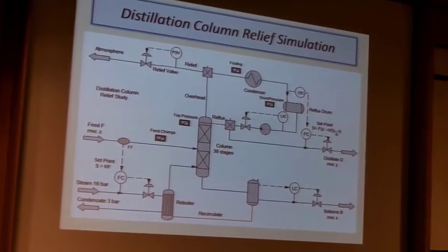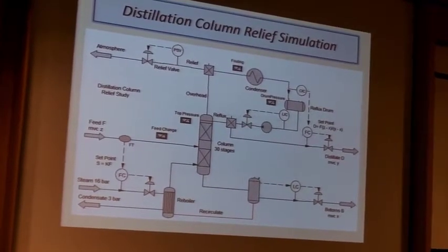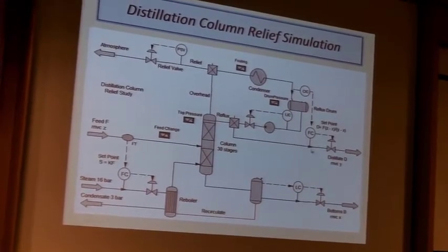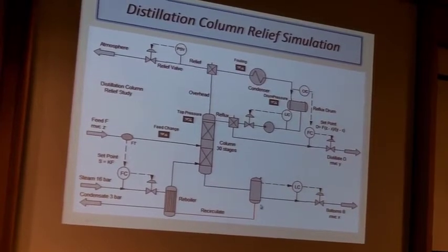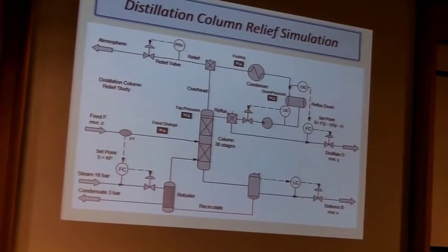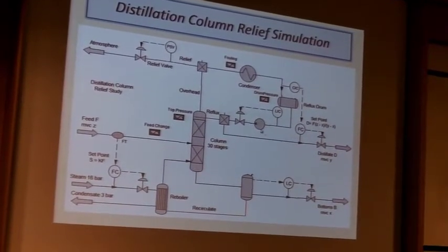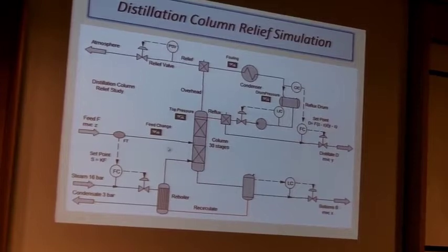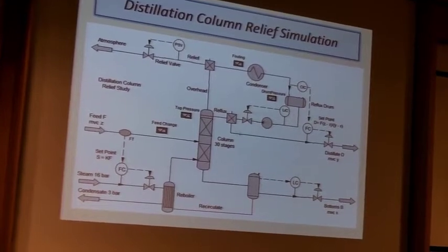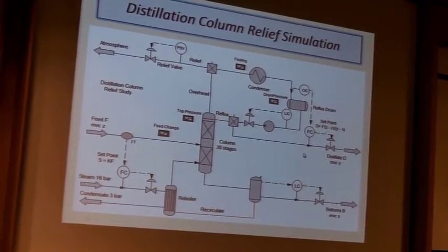The bottom line of this is you can't do a control system without, you can't transgress the mass balance or energy balances in a piece of equipment. The control system has got to comply with that. What you do see a lot is level control on here and level control on the reflux drum. Nightmare to control, because what you're basically saying is you're controlling the mass balance at both ends, and you can't do that. So what's decided from the feed and the operation is the distillate takeoff rate, and then the reflux flow is dependent upon the boil-up rate and the distillate takeoff.